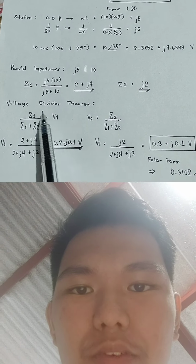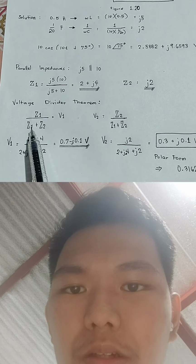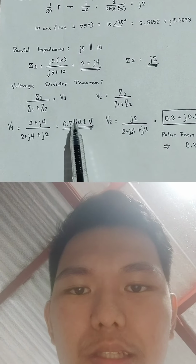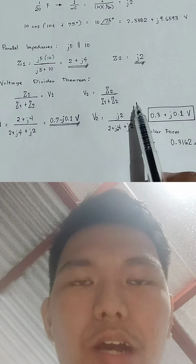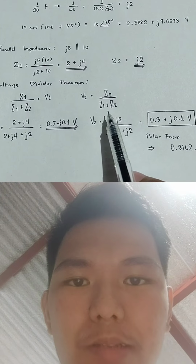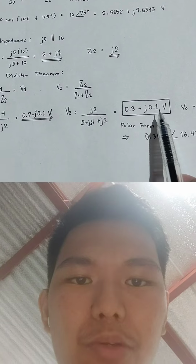Using the voltage divider theorem, the formula for V sub 1 is Z sub 1 over Z sub 1 plus Z sub 2. It is equal to 2 plus J4 over 2 plus J4 plus J2. It is equal to 0.7 minus J0.1 volts. For our V2, V2 is equal to Z sub 2 over Z sub 1 plus Z sub 2, J2 over 2 plus J4 plus J2, which is now equal to 0.3 plus J0.1 volts.